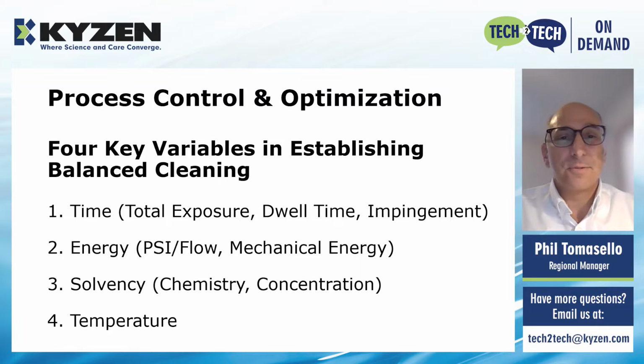There are four key variables in established balanced cleaning, very important variables, including time, energy, solvency, and temperature. Time being total exposure, dwell time or impingement for aqueous cleaning. Energy, you're talking about PSI, flow, mechanical energy. Solvency, of course, being chemistry and the concentration of that chemistry.